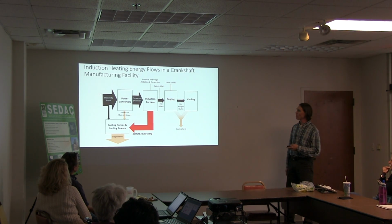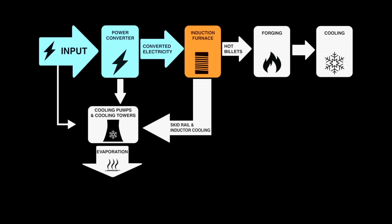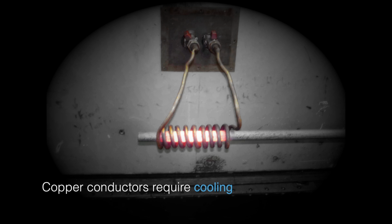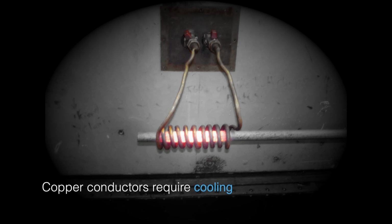The thickness of the arrow represents the relative proportion of energy going in. So we have the electricity input, and some of that's bleeding off for cooling pumps and cooling towers. In the induction furnace you're trying to heat up metal, but you have these copper conductors bringing electricity in. Well, you have to cool those things off, otherwise they're going to melt.